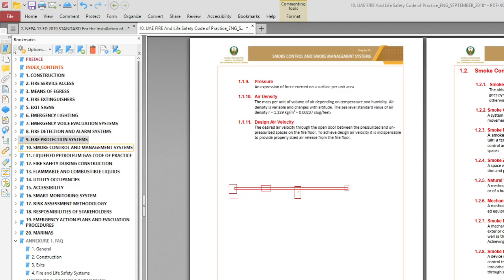for the sprinkler. So this is the hydraulic calculation. If I go by the pipe sizing method, I will say yes, 225 GPM is okay for light hazard or ordinary hazard to protect my spaces. But there is also a pressure drop calculation, which is based on the Darcy-Weisbach formula, and that is based on the K value.